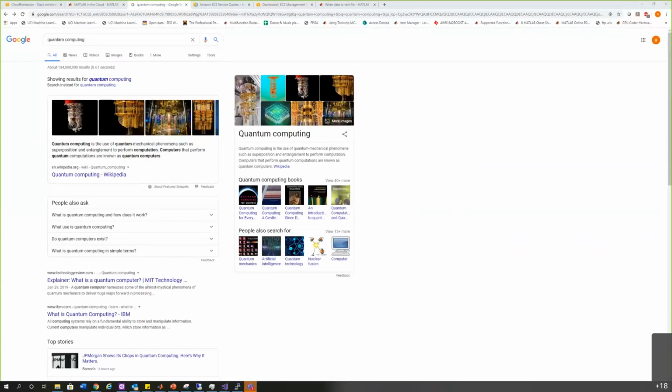But as part of my work, I had one of the algorithms deployed on a GPU, and it worked together with the FPGA. That algorithm was a little more complex. It was not straightforward DSP. It involved a couple more steps, and translating that algorithm to fixed point, then from fixed point to Verilog code, and from Verilog code to realizing it on an FPGA target was virtually impossible at that point.